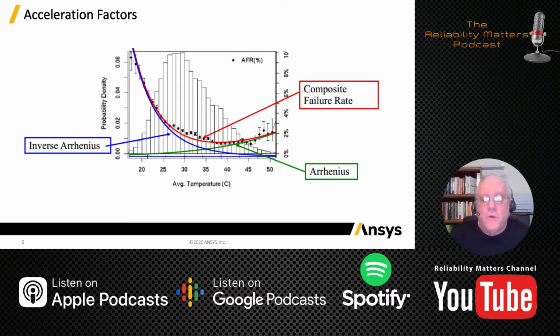However, there are also a number of non-trivial situations that are driven by inverse Arrhenius relationships. And largely these are mechanical kinds of things, latches, switches, things like that. But there's also an inverse Arrhenius relationship inside CMOS semiconductors. So we'll talk a little bit more about that in a subsequent slide. So in reality, what you're looking at there is a composite failure rate of both failures that happen more often at higher temperatures and failures that are more prone to happen at lower temperatures.